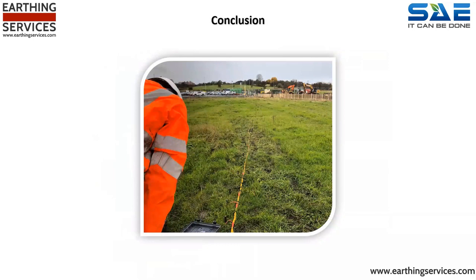When it comes to electrical earthing systems, there are several factors which will determine how well it works, being the resistance of surrounding mass of earth, i.e. how well it discharges electricity, the inherent resistance of the conductors, i.e. how well the conductors discharge electricity into that surrounding mass of earth, the contact surface area of the conductors, i.e. how much conductor interfaces with the surrounding mass of earth, the total discharge zone of conductors, i.e. what's the footprint of the conductor network, and the resilience and longevity of the conductor network, i.e. how reliable is that conductor network on an immediate and long-term timescale, meaning the conductors work today, will they tomorrow, will they in a decade, and so on.